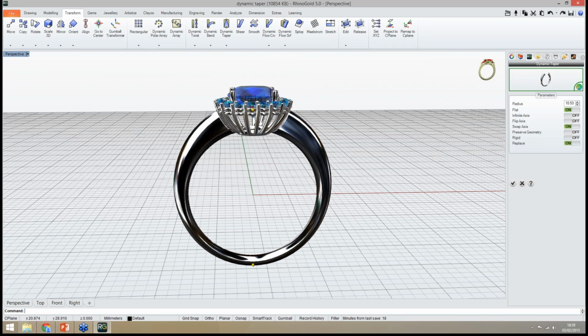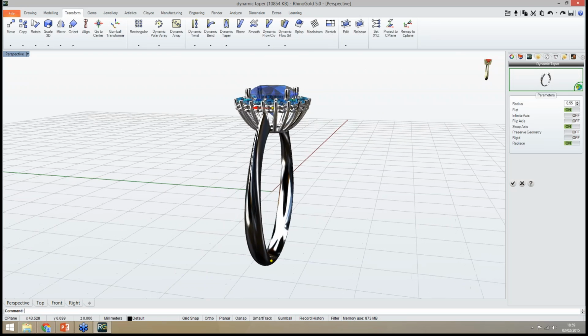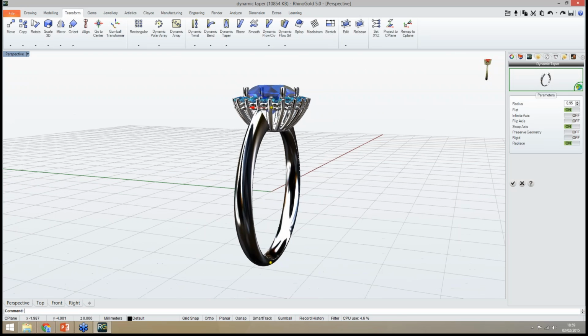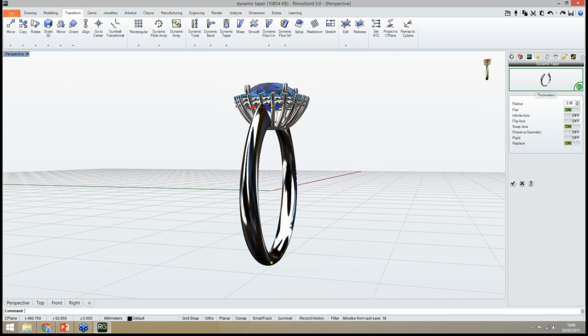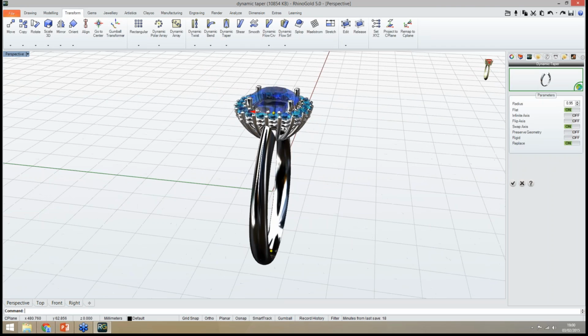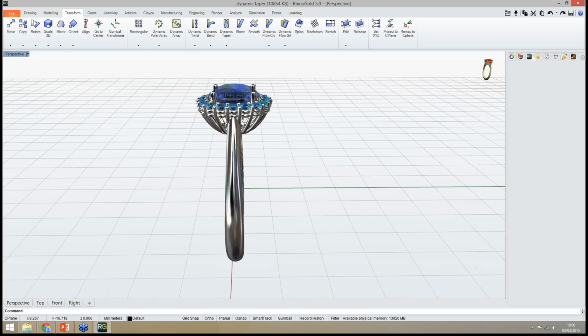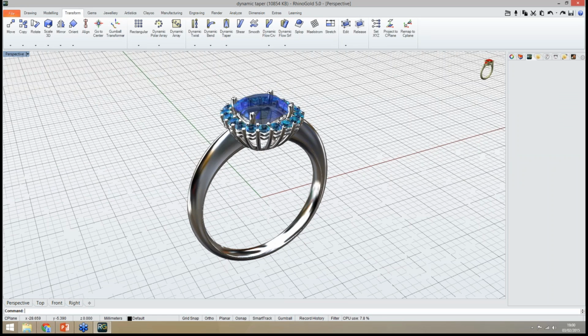We need the training, Pedro. Okay, now here we go. So easily we taper the objects. We have the option to define where I want to start the taper, from the middle, from the bottom. So easily we can adjust the parameters, and here we go. In 2 clicks I have one object tapered.